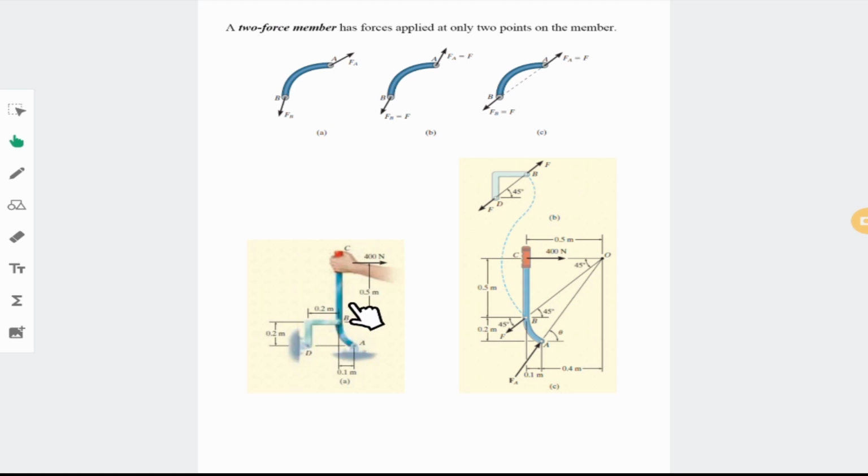If you do that, you cannot solve this, because you would get 4 unknowns in total for this part, and you have only 3 equations, and by having 3 equations you cannot get 4 unknowns. You should be careful about these parts. There is one hidden piece of information here, and that's the angle of the force, which is like this.